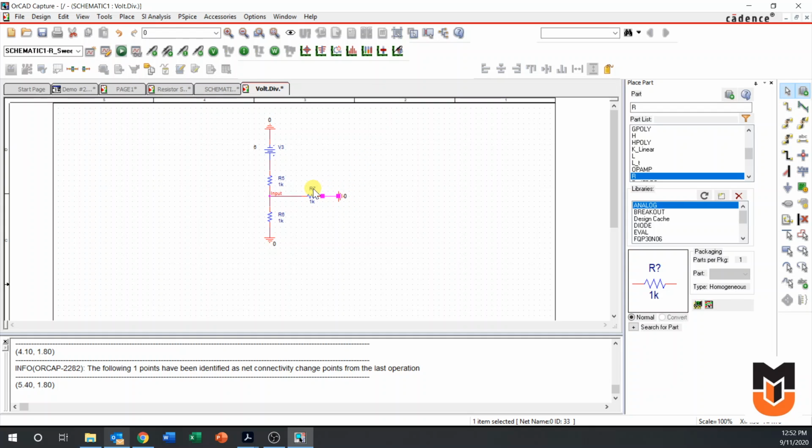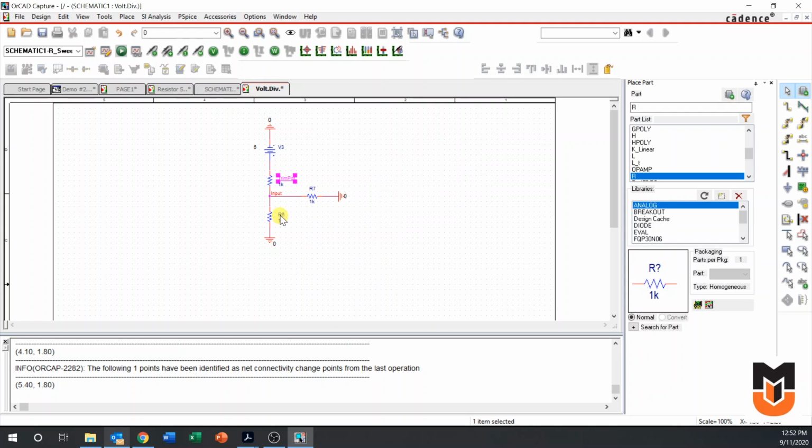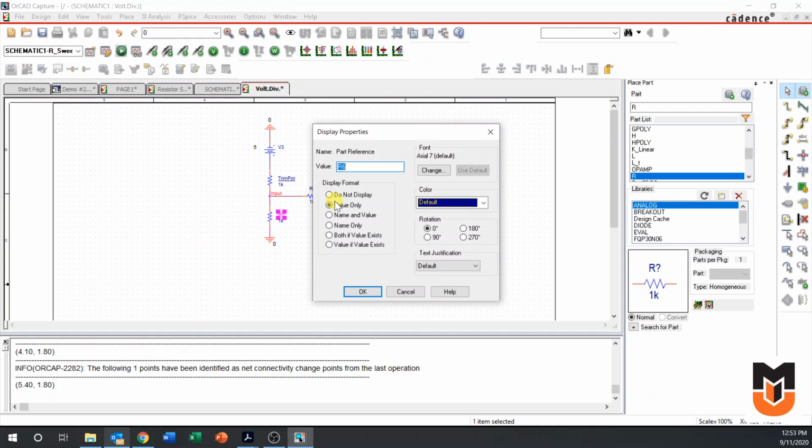If we want, we can label these so it's a little clearer. This would be, for instance, our R going into the op amp, whereas these would be part of our voltage divider. What we'll see in the lab is we can actually use a trimmer potentiometer, which is an adjustable resistor, and this is just going to be the resistor for our voltage divider.